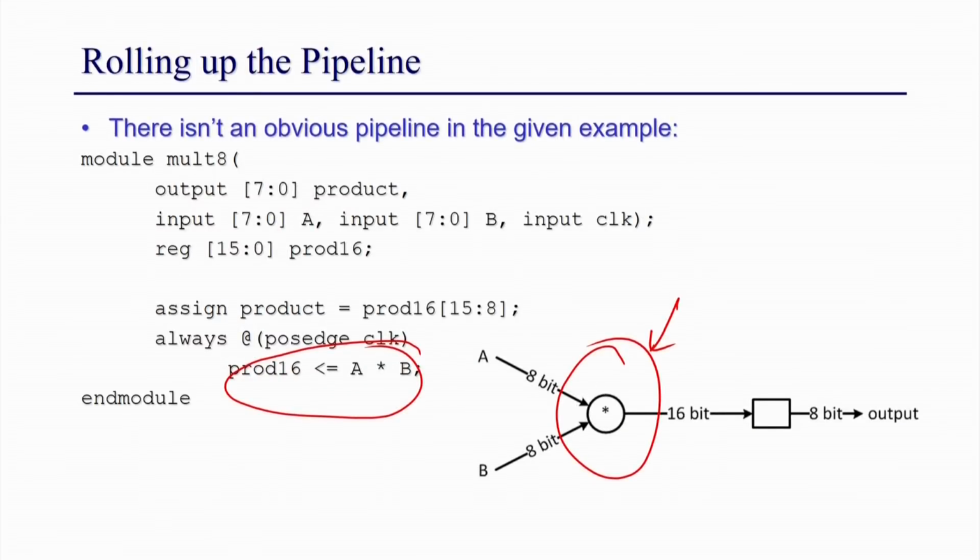This is also possible, and sometimes you have to do this kind of optimization just to achieve your target area, because maybe in your FPGA target your design does not fit. You need this kind of small change in your design so that the whole thing gets placed in your FPGA. In an FPGA the number of DSP blocks is fixed, and the LUTs and logic units are fixed.